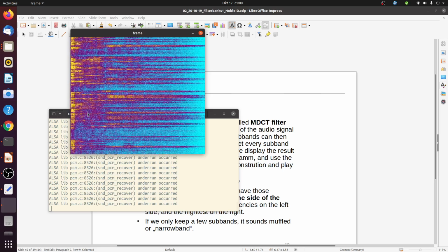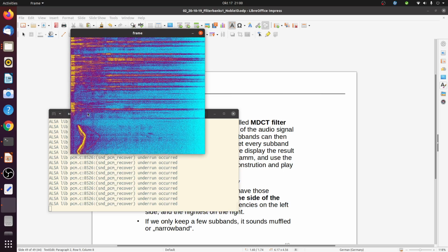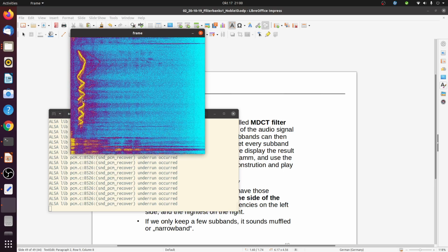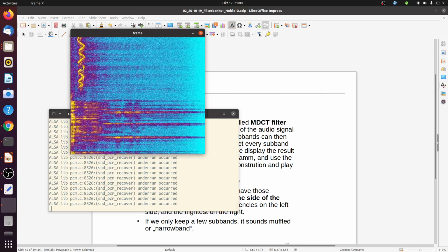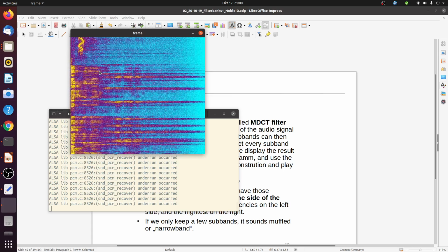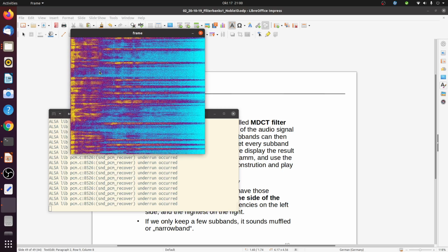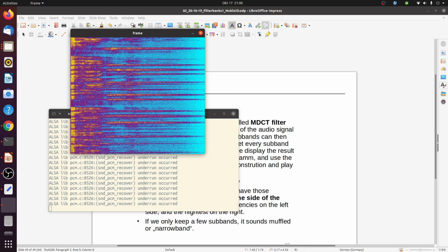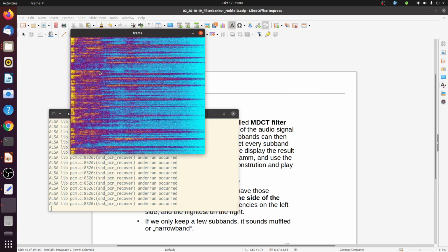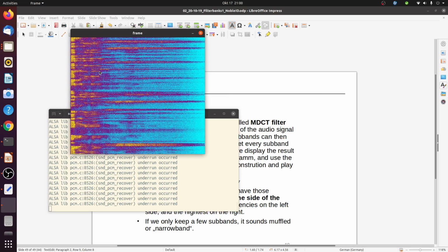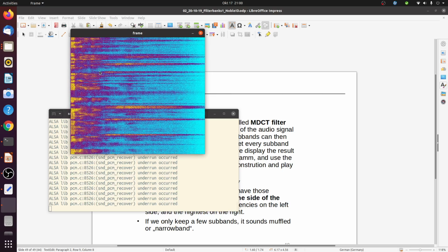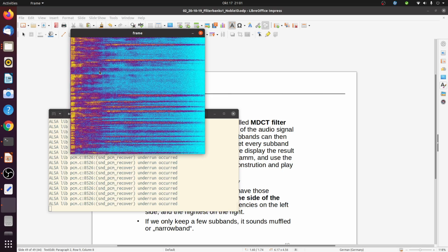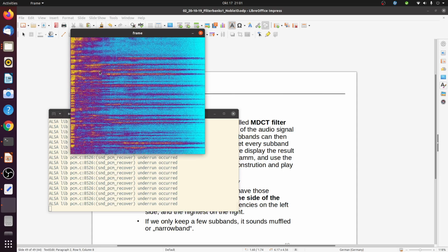So let me whistle. Here you can actually see the echoes from my whistling. There's some offset, and this is actually how radar works, right? Radar is doing the same thing. They use changing frequencies, and from this frequency they can then estimate the time delay from the reflected signal. So actually, we could do a sound radar this way by having a speaker with a changing sinusoid and then just looking at the frequency which is returned, which gives us an indication of the distance from the reflection.